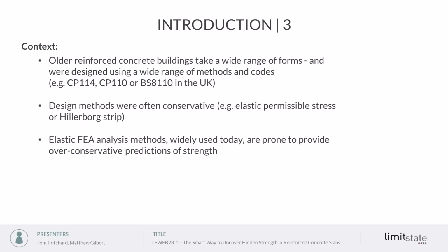So, for example, the Hillerborg strip method is still sometimes used. It's quite conservative, and the same elastic permissible stress design methods are also very, very conservative. Today, we're still using elastic methods via finite element analysis. Unfortunately, they're also prone to provide over-conservative predictions of strength.